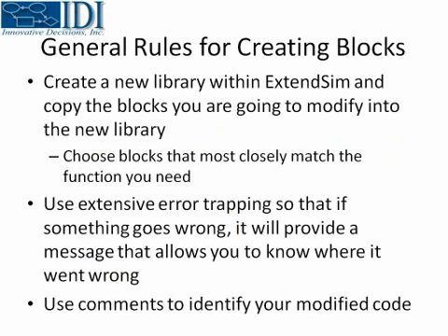Okay, a couple of general rules for creating or modifying blocks. Some of these are lessons I learned the hard way, and other ones are things that are right out of the Extend reference manual. The first thing is, if you're going to create or modify ExtendSim blocks, you want to create your own new library, copy the ExtendSim blocks from the installation of the software over into that library, and then work on those copies.